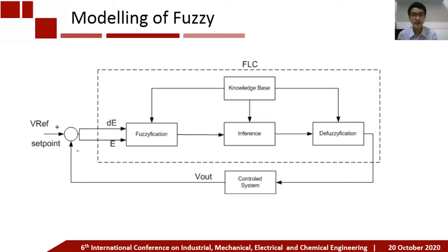The fuzzy logic controller has three main components: fuzzification, fuzzy inference system, and the defuzzification. Fuzzification is the first stage of the fuzzy inference process. At this stage, the input data is received and the system determines the value of its membership function and convert numerical variable into linguistic variables. Membership function give meaning or define linguistic expression to be number that can be manipulated. Fuzzification obtains a value and combines it with the membership function to produce a fuzzy value. Fuzzification is the process of determining an input number for each fuzzy group.